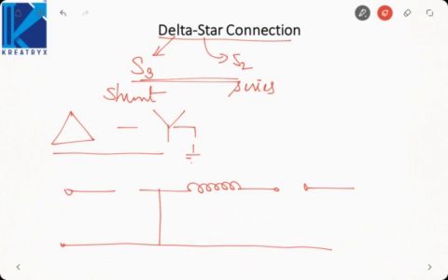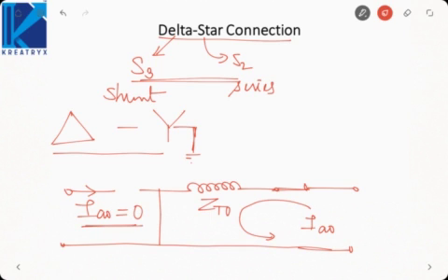So here zero sequence current on both the sides of the transformer will be 0. Okay. Now suppose if we ground this neutral, then this switch will be shorted. Then zero sequence current can flow like this. That is, zero sequence current can exist in phase as well as line of the star connection and the phase of delta. Here zero sequence current will be 0.